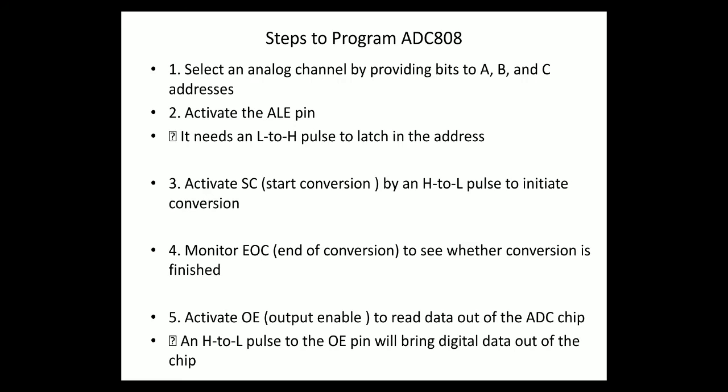Third step, activate SOC, also called SC, start conversion. This needs a high to low pulse. So a 1 to 0 pulse is required to initiate the conversion. Then end of conversion, to see whether the conversion is completed or not. Your job is only to monitor it because it's an output signal.